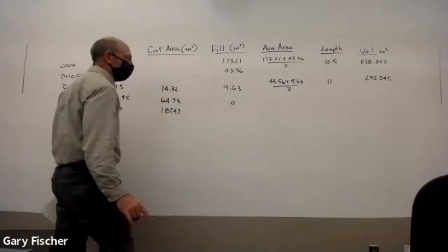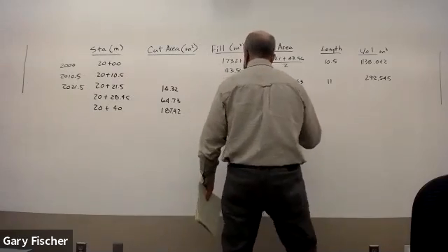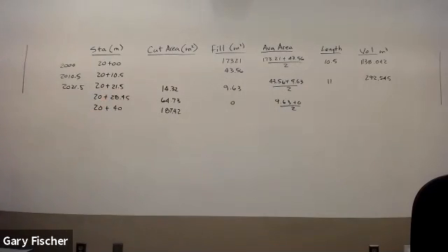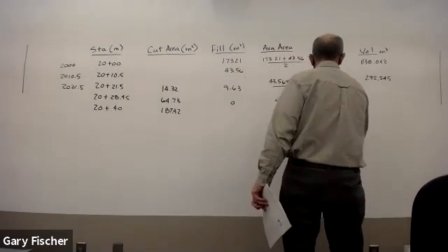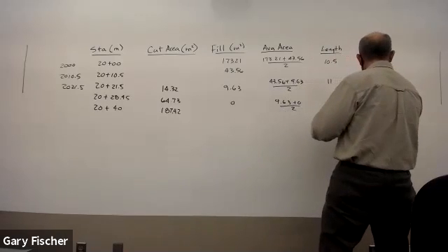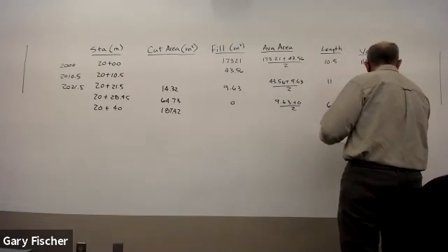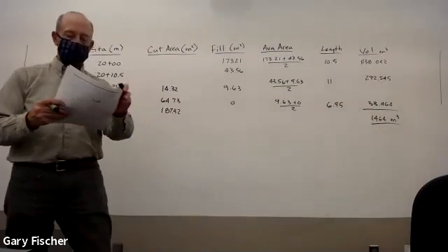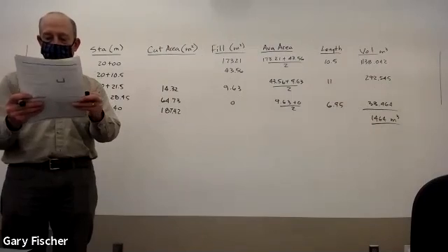Now, you've got fill here but none on the next station, so it's essentially zero fill, and you take the average of those. So it's 9.63 plus 0 divided by 2, multiplied by the distance here: 28.45 minus 21.5. I get a volume of 33.464. If you add them all up, I get 1464 cubic meters. And what are the answers that they give you? Most nearly, I believe it's B.